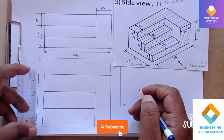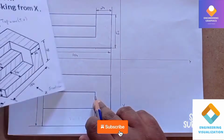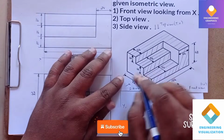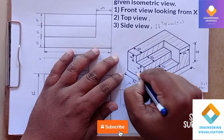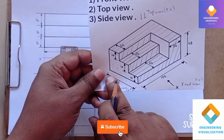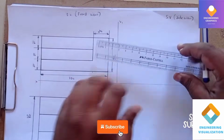So we should dark it. Okay. Now we can mention dimensions here. So each of these top faces has a dimension of 24. Now we have to draw the side view. You can see like side view we should construct. Okay. So this is what I will be shading with the help of dots, the side view, so that we get a clear understanding of how to do that. Okay. So you can see adjacent to the front view we have the side view. Okay, I'll be drawing the projection lines here.